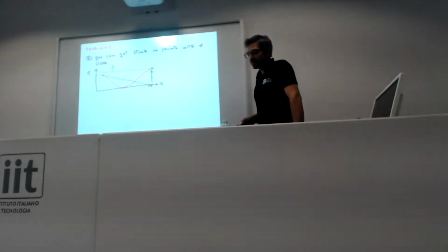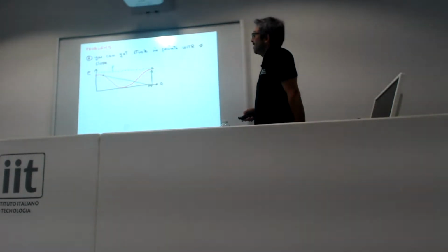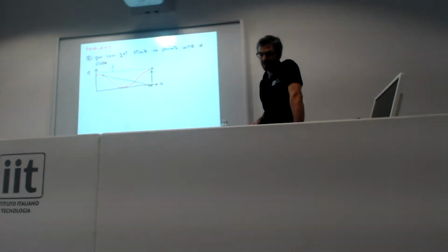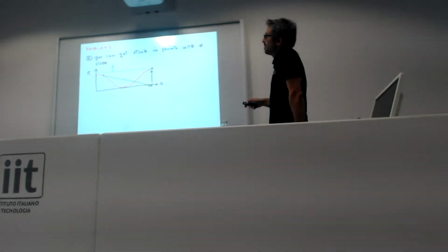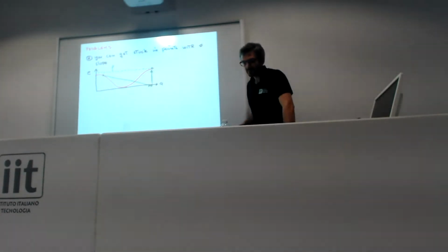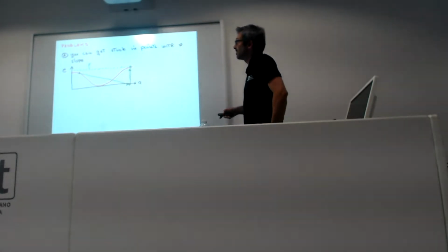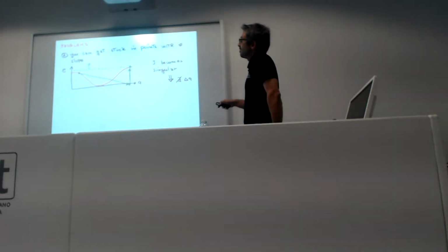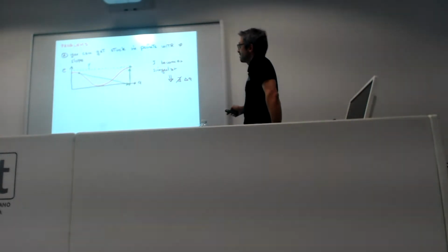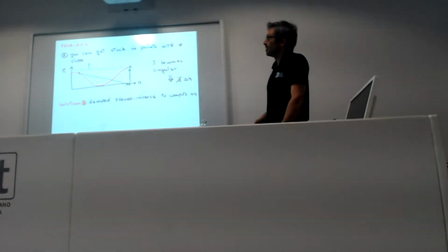There are some problems that you can get in this approach, and one is that this algorithm can get stuck in points where the slope is horizontal. So let's say the Jacobian in this case is 0, so it becomes singular, because if you have a singular Jacobian, you get a horizontal slope, and then you're not able to find the intercept and you can't find the delta Q value.